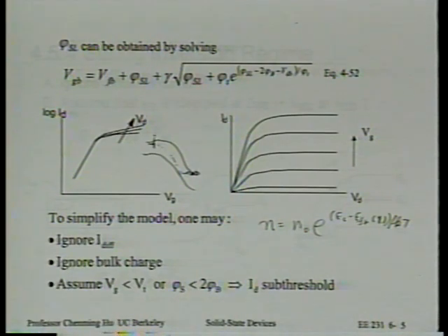Yes. I thought always that either the drain or the source, it doesn't really matter, one of those was always tied directly to the body. And actually, that statement is not true. It may be easier to think that one of them is tied to the body, such as the source. But in a real circuit, many transistors have neither the source nor the drain tied to the body. So just accept that, all right? And later we can even see some examples of how this is the case.